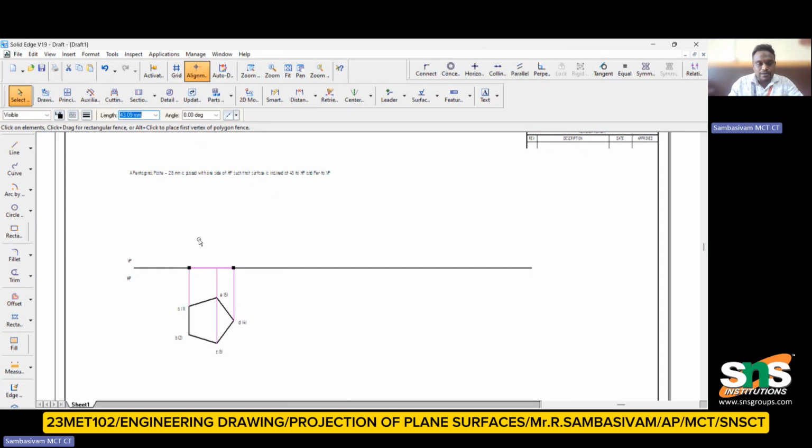To understand how the view has been identified, I am going to use the red color for clarity. Again, I have to transfer the total length of 43.09 on this line. This is the final view we have obtained. From this line, I mark the total length of 43.09 at an angle, as they have given, inclined 45 degrees to HP. So I have to make it 45 degrees. The line has been drawn like this, and the red line has been converted into this structure.